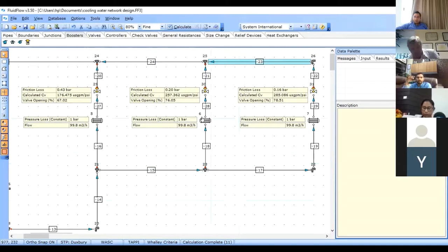All right. So let us proceed. One more doubt. Yes, sir. What if we have the control valve or the restriction orifice before the exchanger? Will it work fine? Typically, it will be on the downstream of the exchanger. The reason being, if I keep it on the upstream, then there is a chance that I'll starve this exchanger of the water or whatever fluid it is.